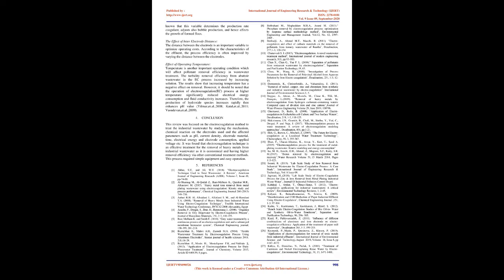Effect of EC time. Reaction time is one of the most significant operational parameters for all electrochemical treatment processes, as with the increase of reaction time, corrosion of electrodes releases higher amounts of coagulant ions in the solution. An increase in reaction time improved the efficiency of phosphate removal. Bibahani et al. 2013. Increase in electrolysis time leads to an increase in coagulant concentrations that has been reported to reduce the floc density, then to reduce their settling velocity.